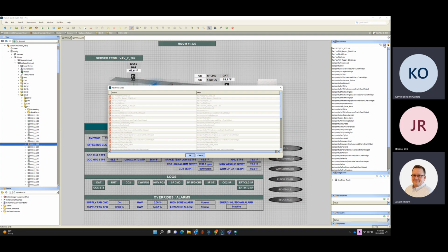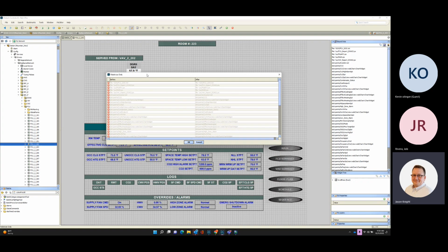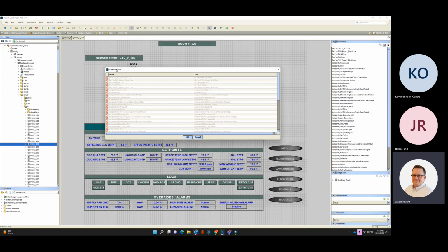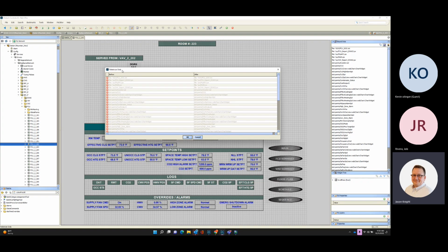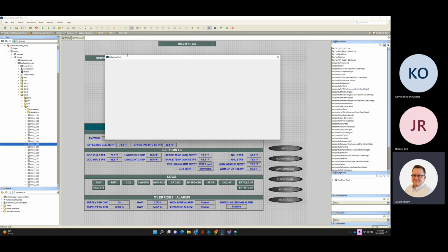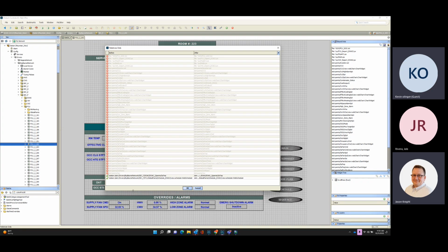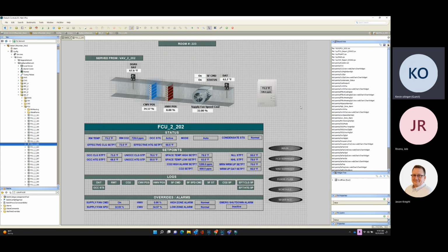Because we've always used templates as a statement, and now relativized and template is similar to us from a layman's standpoint, correct? Yeah, the nomenclature that Niagara 4 uses is relativized ORDs, relativized object resolution descriptors. So between the different software manufacturers, basically, yeah, it's a template. And an ORD is more or less kind of a point. Yeah, a pointer to a point.